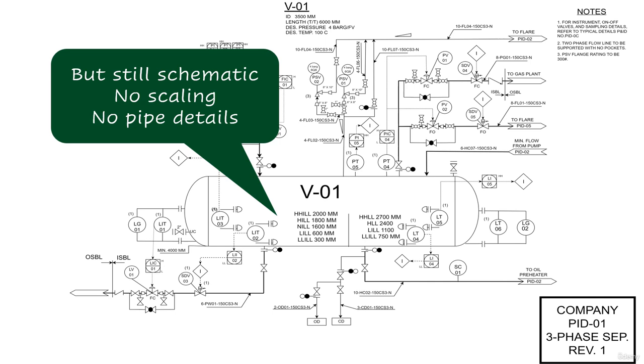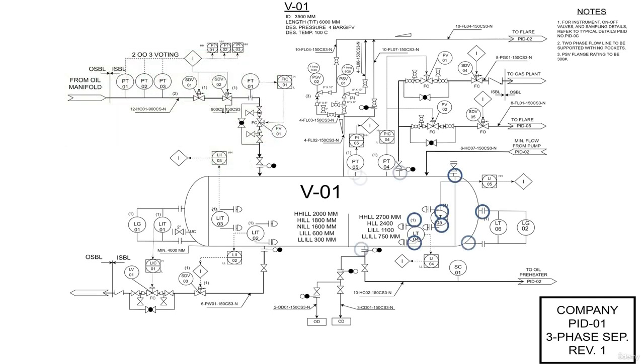So, for example, the P&ID is expected to show all the nozzles in any piece of equipment and what these nozzles are connected to. Shall they be connected to process lines or to utility lines or to instruments or to pressure safety valves? Shall they be just blinded? All this should be reflected on the P&IDs.